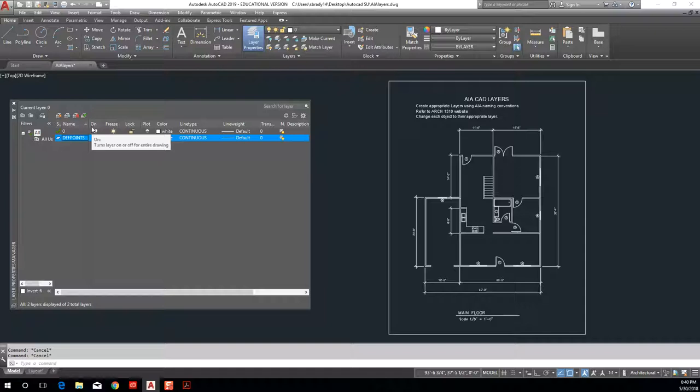All right, so what I mean by that is that when I assign a layer to an object, I'm going to do it by architectural element. Okay, and what that means is that in AutoCAD, all of the walls go on one layer, all of the windows go on another layer, all of the appliances go on a layer, all the furniture goes on a layer, all of the flooring hatch goes on a layer. Okay, so I'm going to create layers for every object or architectural element in AutoCAD, which is a lot, right? We'll have a lot of layers, especially when you're working professionally.